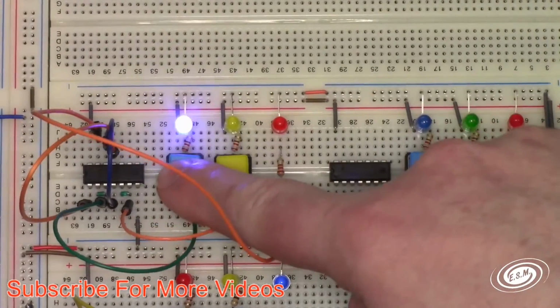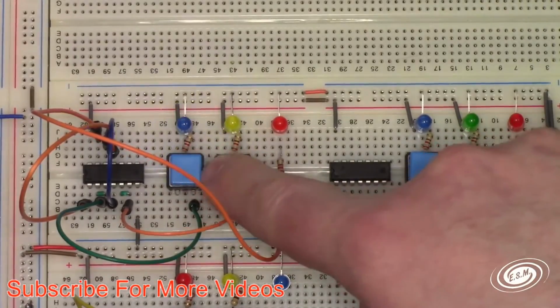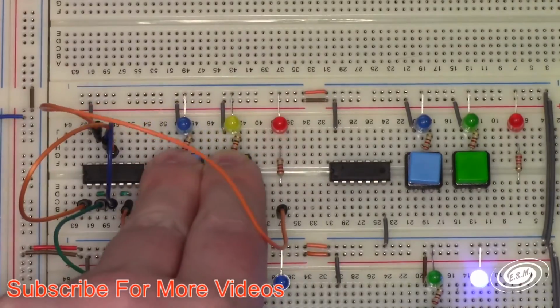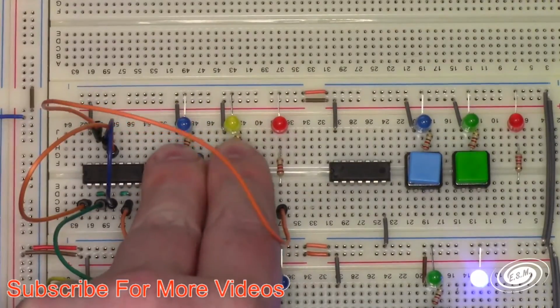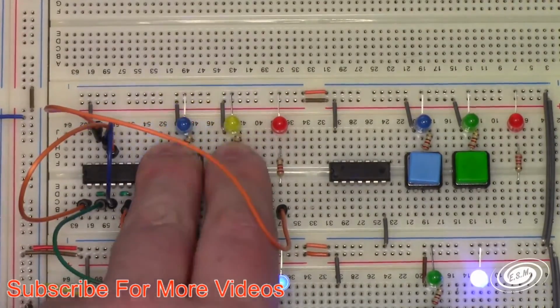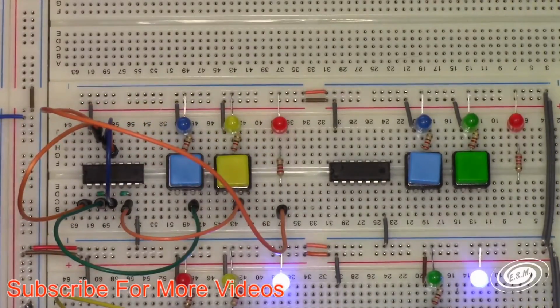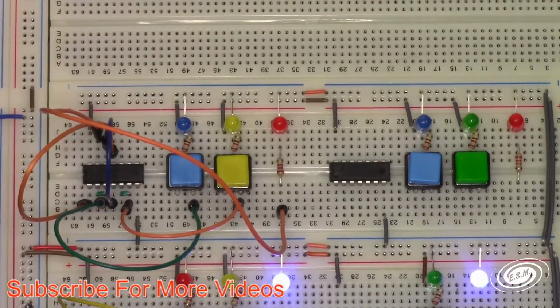So if I press 1, nothing lights. If I press them both, the output lights. So AND: 0, 1, 0, 0, 1, 2, 3, and on 3 they light. So that is NOR gates making an AND gate. Now we're going to make an OR gate.